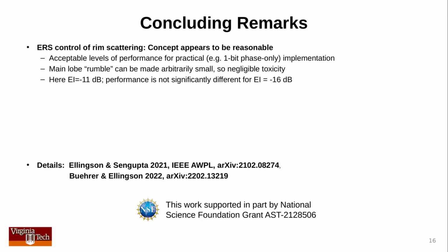We've analyzed the -16 dB case, and we find that everything works just as well. That's counterintuitive, but it turns out that the loss of power available to the ERS is nicely offset by the associated loss of power available to the much larger non-reconfigurable portion of the dish. So, ERS technology appears to be robust to varying degrees of edge illumination as well.